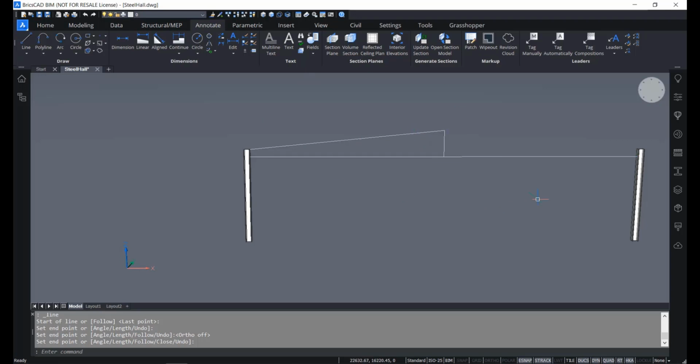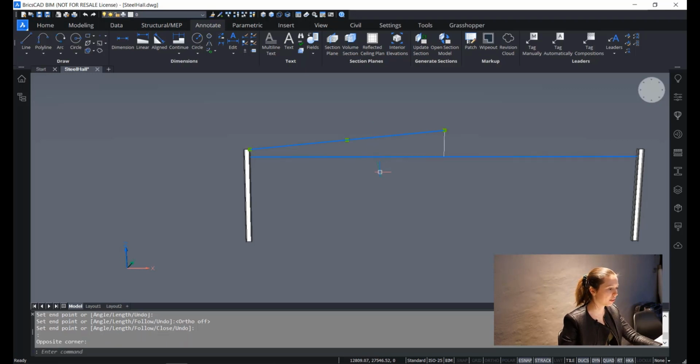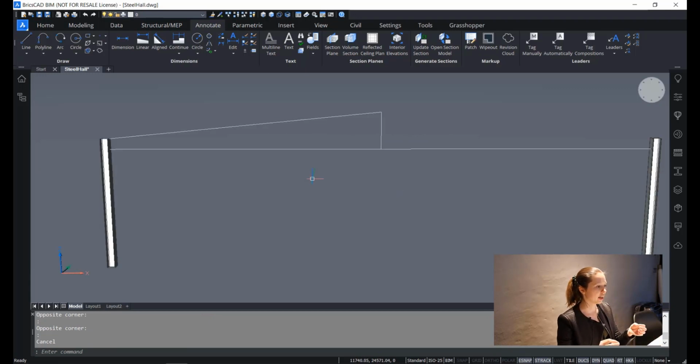So now you have the big beams of your structure, but not the little members that make up the truss diagonals. So what I will do now is I will divide the upper and the lower line into points that denote a specific division of this line. So I will divide the line into an amount of segments, and on each endpoint of this segment a point will appear. So the line will not be literally divided into smaller lines, no, it will be just where the division points are, points will appear.